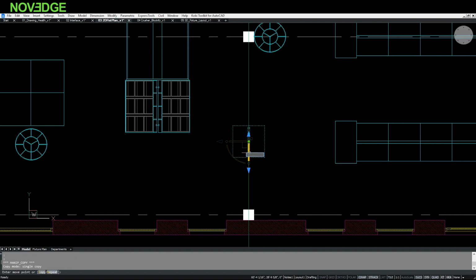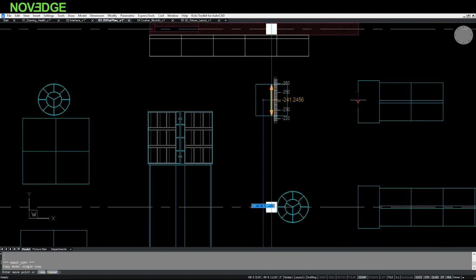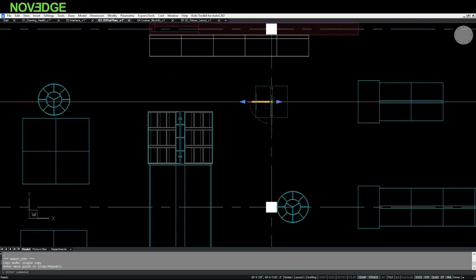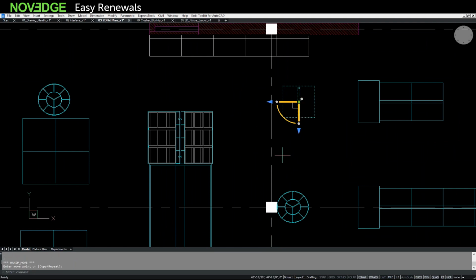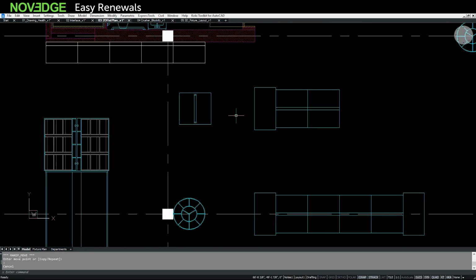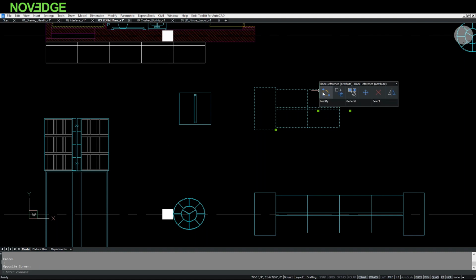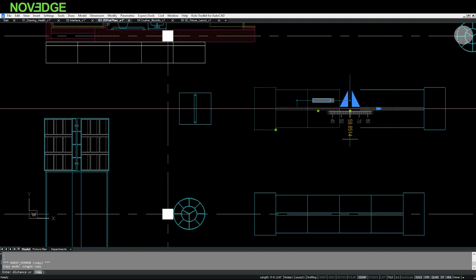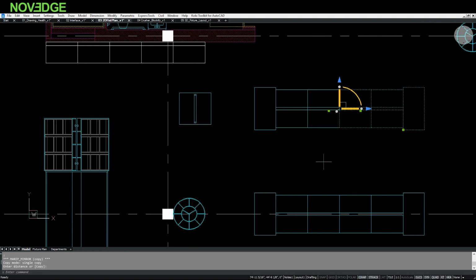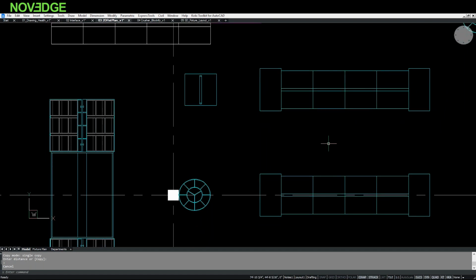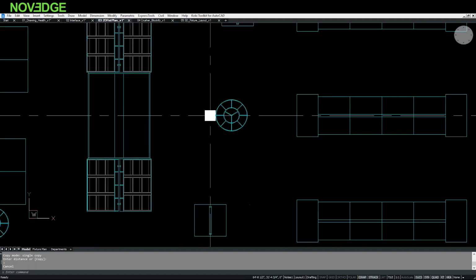I'm going to use the manipulator to copy this table up to the center line point of that, and then move it over and put it in place. Again, the manipulator is very fast. I'm not entering any commands. I'm just using the tool in a heads-up display. I can select multiple items, so I can select this series of gondolas and tables and such. Again, I deploy my manipulator and use the arrow to mirror this. I'm going to mirror it about the center point of that. And then again, very quickly, I'm able to manipulate those items without any command input.